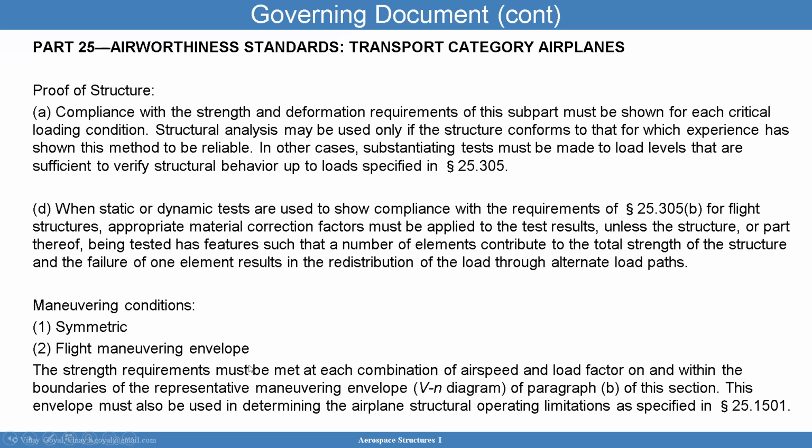The strength requirements must be met at each combination of airspeed and load factor. And we want to make sure that we're fully encompassing the VN diagram that we talked about. And we'll be talking about that later. That's the speed load factor diagram that we talked about. Okay, very important consideration that I don't want you to forget.